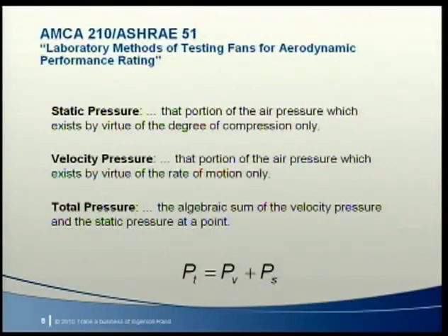Sure. Today we're going to talk about fans, and I don't mean Houdat fans. I mean mechanical fans, the heart of every air distribution system. Fan fundamentals begin with air pressure. Air in motion has both potential and dynamic energy. Potential energy relates to static pressure, like air in a balloon. Dynamic energy relates to velocity pressure, like air pushing on a sail. The total pressure of air in motion is its static pressure plus its velocity pressure. A fan increases the total pressure of air passing through it.